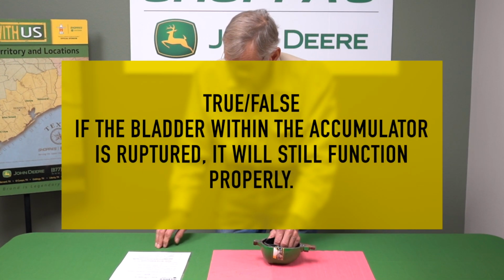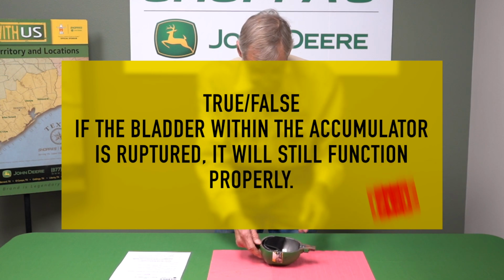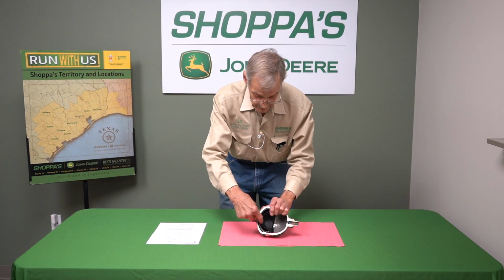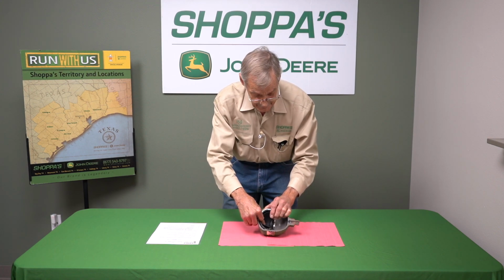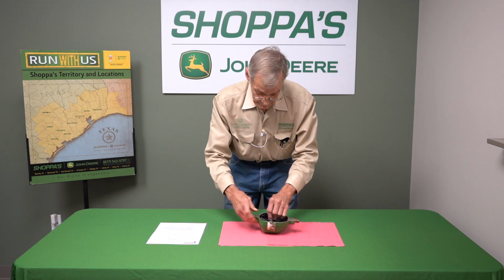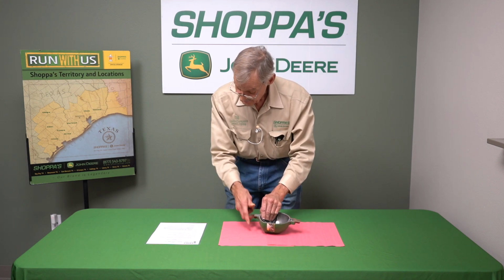If the bladder within the accumulator is ruptured, it will still function properly. There again, if this bladder ruptures, then it's going to collapse totally, and you're not going to have any reserves back in this area, nor will you have any dampening effect. So that's false.